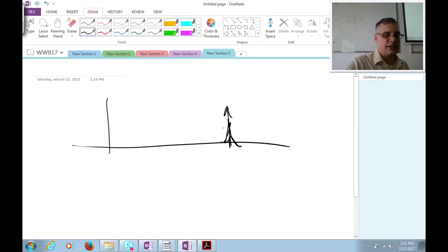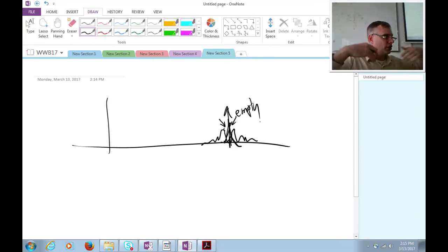If I use balanced code words, then regardless of how my signal spectrum looks, I know that this area in here is going to be empty spectrally. And so that means that I can decode the signal with minimal problems. I'll get the maximum sensitivity, the farthest range in that scenario.